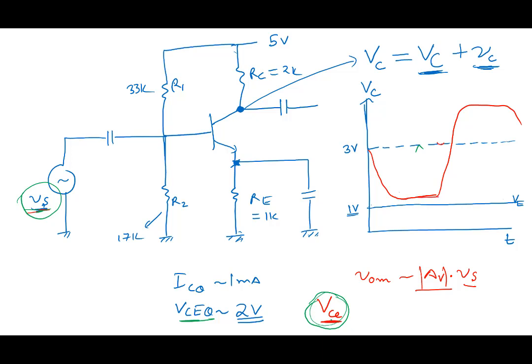You'll see clipping, and this value is 0.2. Remember what we said, once it goes into saturation, the voltage is almost 0.2. It's like clipping. It can't go below this. So if you push your signal hard, drive Vs even more and more, you will see clipping occurring.